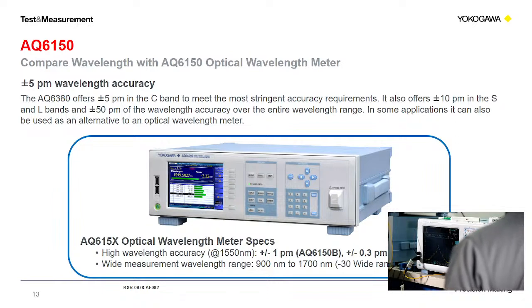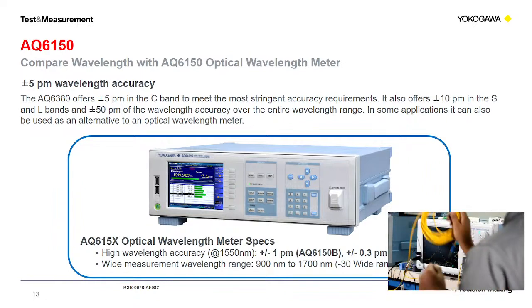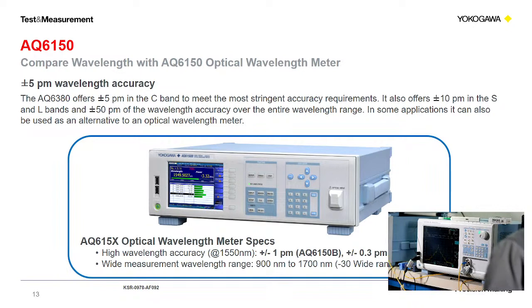But what we've noticed is that customers have noticed that the spec has improved so much that they're reconsidering. If they only need 5 picometer resolution on their measurement, they may not need to buy a separate wavelength meter. They could just buy one OSA that will cover both the wavelength accuracy specs as well as the 5 picometer resolution. So kind of replacing 2 instruments with 1.